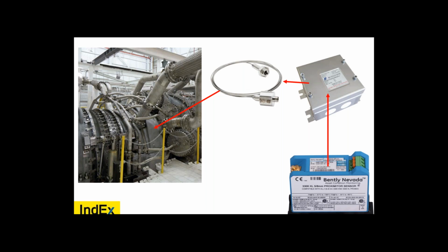So if there's EXMB inside of an EXE luminaire, that MB probably has to do with a starter or a transformer, something like that. So an EXE luminaire is not just EXE. You'll never have just an EXE luminaire. It'll have other protection techniques internally for the other components inside. If it's EXD, well, you don't need to have any other EX protection technique inside.